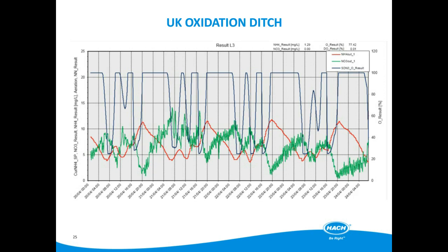During the 4 days shown, the aeration system only operated at 100% for 49% of the time, and 25% of the time the aeration system was operating at or below 50% aeration intensity. During all of this time, the plant never exceeded more than 12 milligrams per litre ammonium with a consent of 20. Therefore, this energy saving was achieved at no risk to compliance. There may be additional unseen benefits of lower stress on the mechanical drives as well.